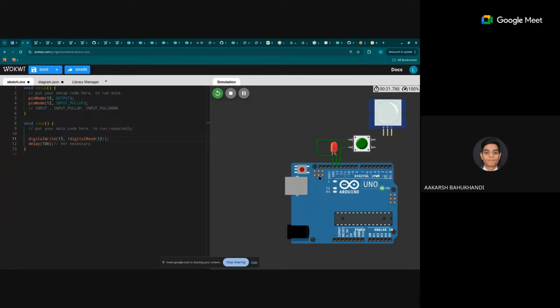Before, it was taking all the voltage to itself instead of the light bulb. Actually, we didn't supply voltage to the LED with this button. We supplied voltage to pin 12, or drained it, using this. So, sir, I assume you will press this. What will happen? The voltage at pin 12 will be 0, correct?